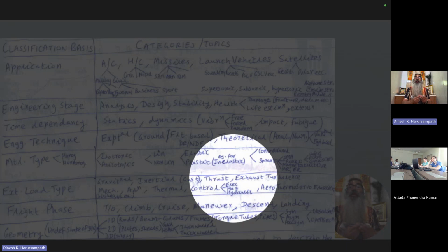Saint Venant's principle says that if you go a distance which is of the order of magnitude of the cross section into the interiors, then it doesn't matter how you're applying a load at this point. I can apply either a concentrated force, or I can apply a distributed pressure, both of which have a resultant that is the same as the force that I was applying earlier. And only things close to the point of application of the force will change, that is, within a distance of the order of magnitude of the cross-sectional dimension. But once you go into the interiors, it just doesn't matter which way you're applying the loads. So since from an aircraft point of view, all points in the aircraft are important for us, including points which are closer to the actual application of the load, namely the skin of the wings, or the skin of the fuselage, or the skin of the horizontal and vertical tails, the stabilizers, you do need to take the distributions into account as well.